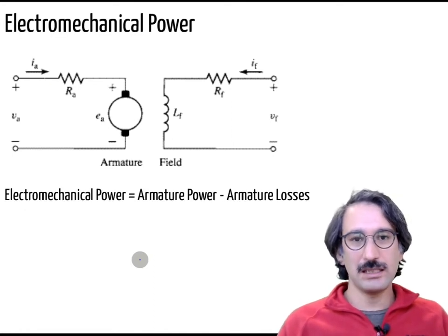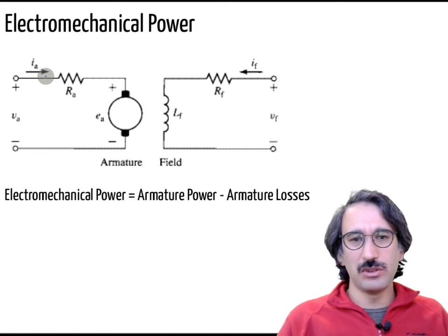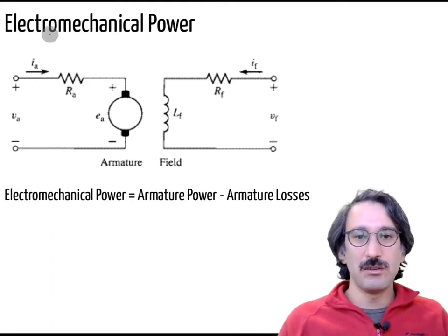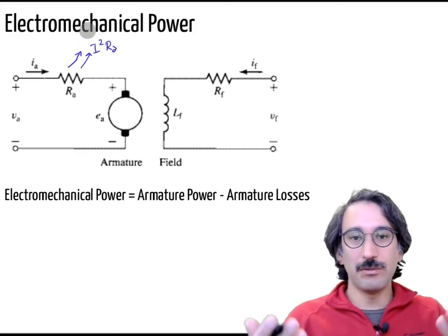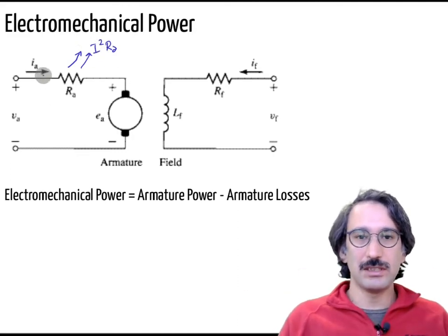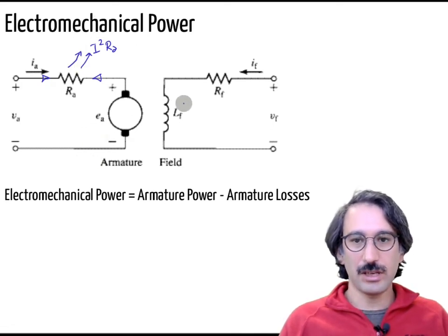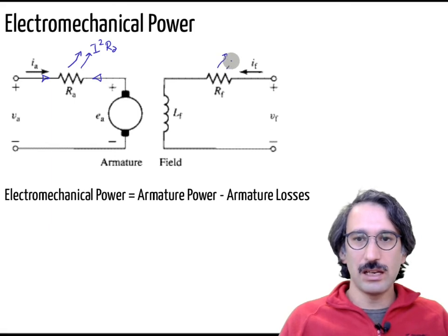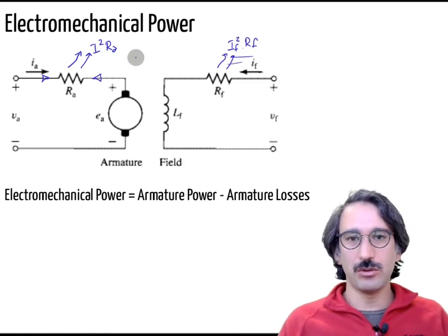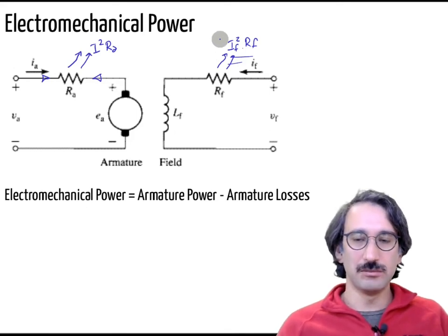Okay, but in any case, of course, we don't have efficiencies larger than 100%. We will also have the losses, and those losses will be proportional to the square. So it is always dissipating some heat. So even if the current is flowing in that direction or the opposite direction, we will always have the armature losses here. Okay, so again, on top of that, you can have the IF field winding losses, but compared to those ones, these losses are mostly negligible.